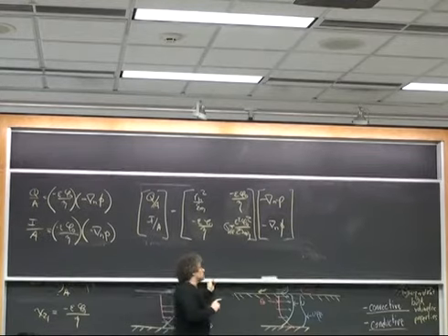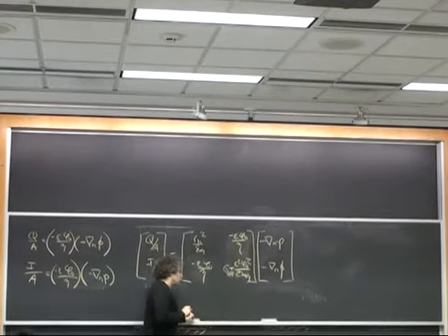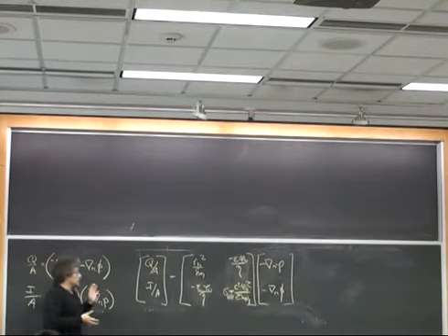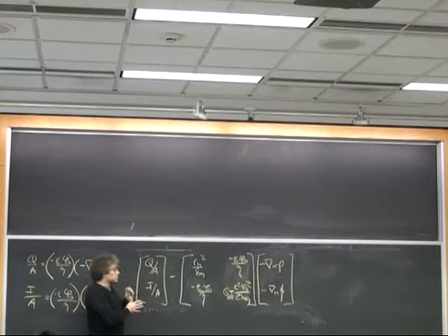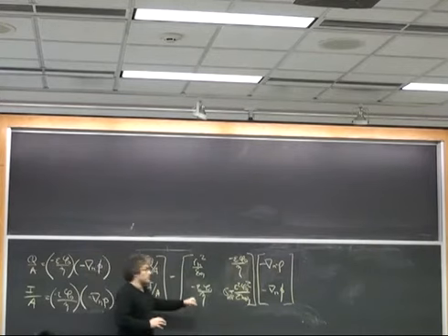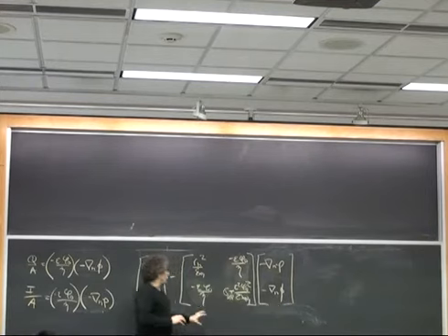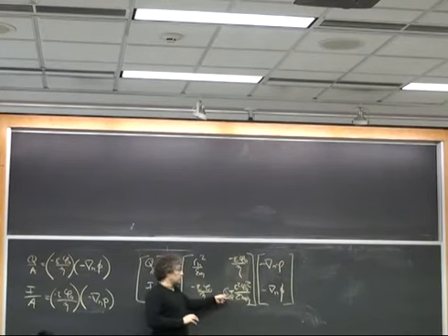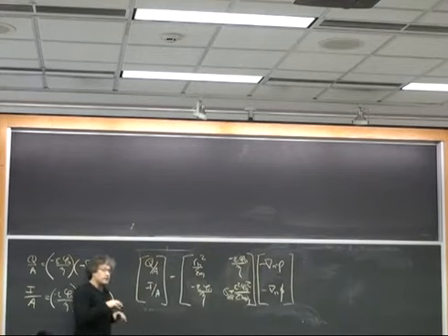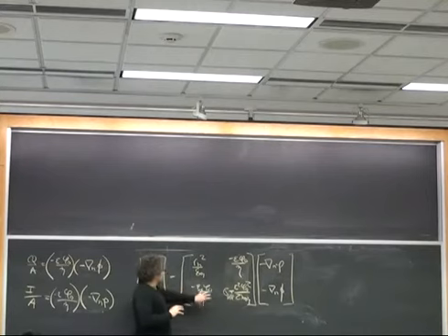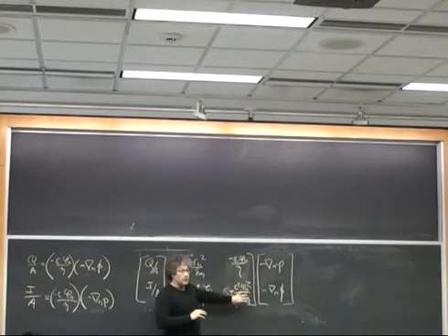Correct. And the reason for the symbols that I'm using all comes back to the fact that this equation is a system equation. It's basically describing what is the total volumetric flux through the system, what is the total current through the system as a function of pressure gradient and potential drop. I'm describing it in terms of bulk volumetric properties like viscosity and conductivity, despite the fact that a bunch of stuff is changing across this domain. When I integrate all these effects, I can use that to define these properties.